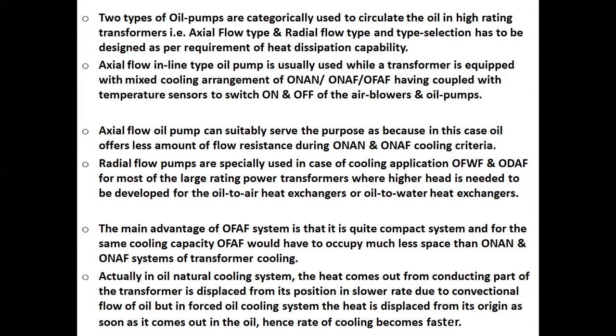The main advantage of the OFAF system is that it is quite a compact system, and for the same cooling capacity, OFAF would occupy much less space than the ONAF system of transformer.